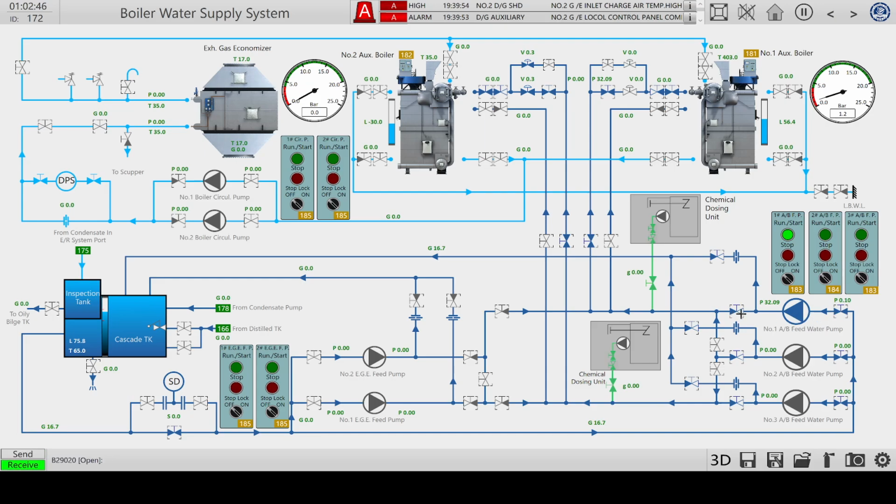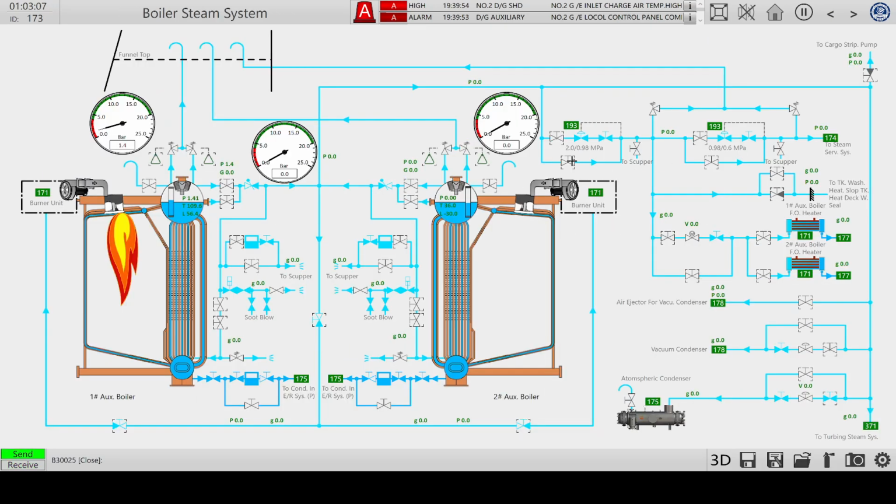First feed water pump is running. It is a circuit. Let's use a rotation method, not a bypass. There's pressure over here, so that's good. This one is filling up the second boiler a little bit. Water is boiling, we do have a little bit of pressure.